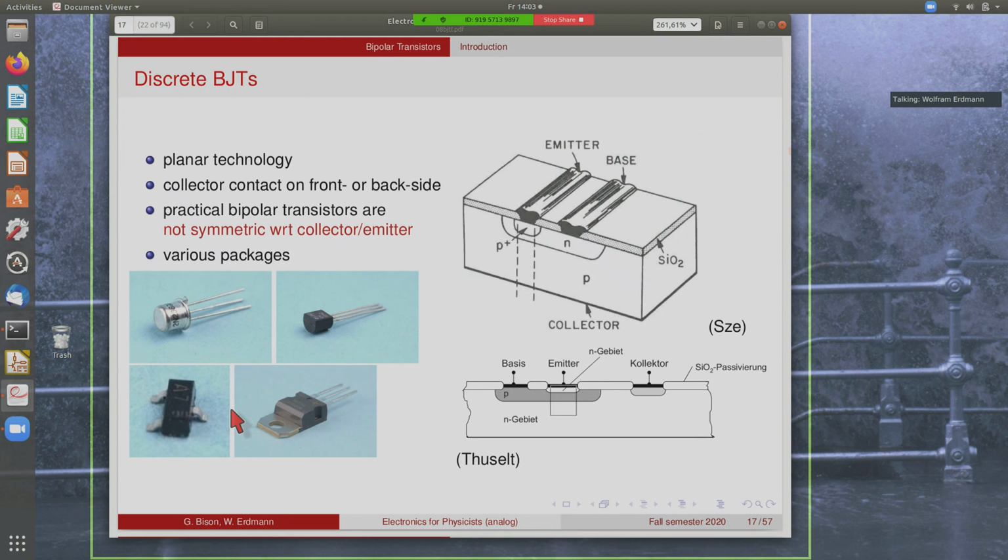Okay, so now what does a real transistor look like? They are mostly not put together by blocks of silicon like the diagram suggested that we've used, but they're fabricated in so-called planar technology. So one takes like a disk of material. Here, for instance, for a PNP transistor, you can take a wafer of P-type material in which you embed then an N region, and inside the N region you put another P region, and then the transistor action is basically happening here.